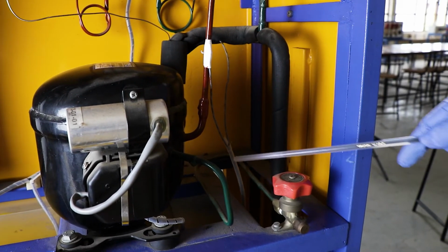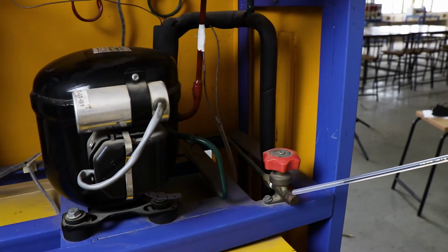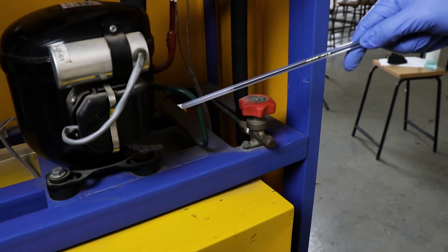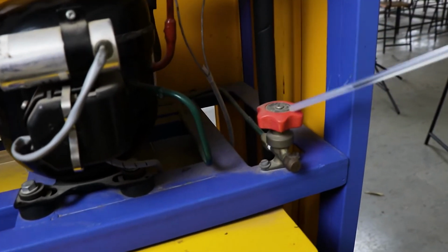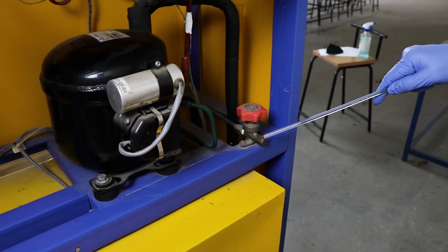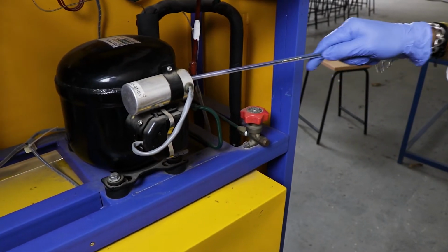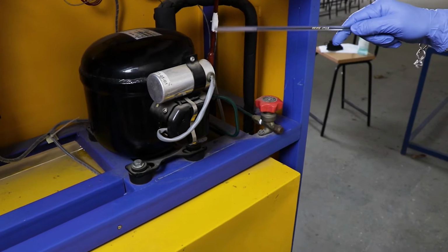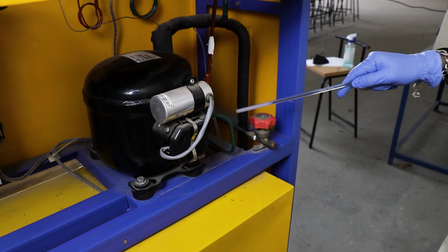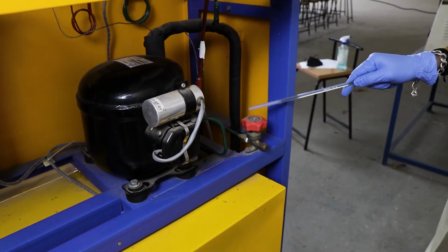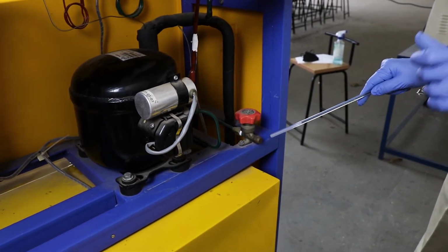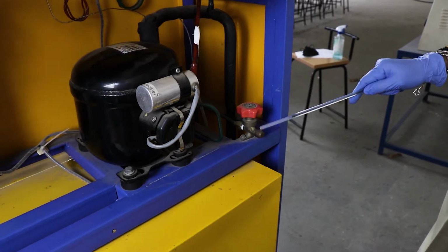Now this green one is an extra pipe which is having a valve here and a perfect closure here. This small tapping of this green pipe is used for charging the whole unit. The whole unit can be charged with the help of this by removing this and by opening this. It can be connected to the refrigerant, and this system can be charged with the help of this, which is closed here. Usually it is a pinched off pipe. In this case here, it is not pinched off. It is closed by the valve and a closing cover here.